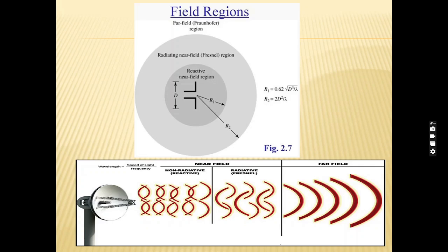Spatially independent of the distance from the antenna. If the antenna has a maximum overall dimension d, the far field region is commonly taken to exist at a distance greater than r = 2d² / λ, λ being the wavelength. The far field patterns of certain antennas, such as multi-beam reflector antennas, are sensitive to variations in phase over their apertures.